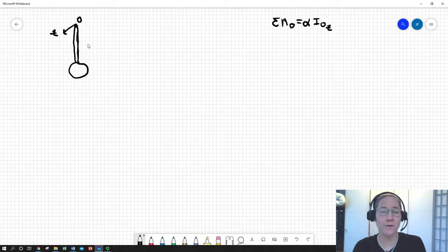And this is what we'll be looking at mostly for rigid body planar motion, because this is probably going to rotate, translate, move somehow in the plane of the screen. So all of the rotation is going to have a vector, kind of our k hat is going to be pointing out of the screen. So we need to know what the moment of inertia is about the rotation axis that's pointing out of the screen. So if you remember back from some of this being introduced at the end of statics, this is known as the polar moment of inertia.